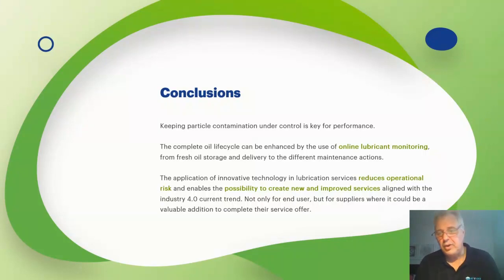So one of the conclusions will be keeping particle contamination under control is key for performance. The complete oil life cycle can be enhanced by the use of online lubricant monitoring, from fresh oil storage and delivery to the different maintenance actions. The application of innovative technology in lubrication services reduces operational risks and enables the possibility to create new and improved services aligned with the Industry 4.0 current trend, not only for the end user, but also for suppliers, where it could be a valuable addition to complement their service offer.